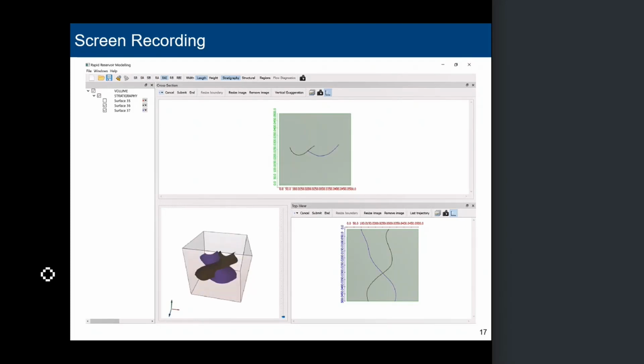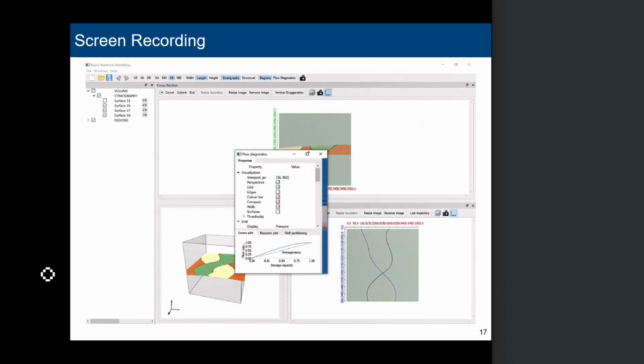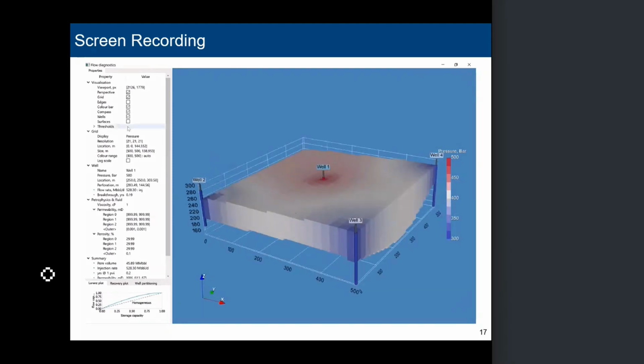We can then select the region below and put in another stratigraphic surface. So here that's the surface at the front cross section of the model. As we go further back into the model, we have another cross section. We say that surface is at a deeper level, so it's dipping away from us. Then at the back of the model, we bring it back to the surface again. So it basically has this bowl-shaped geometry in cross section. Here we've just coloured the different regions of those models so we can differentiate them. And that's it, so within a couple of minutes, the model's built.